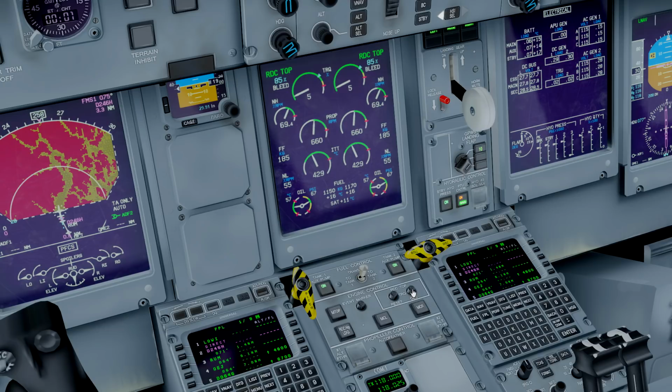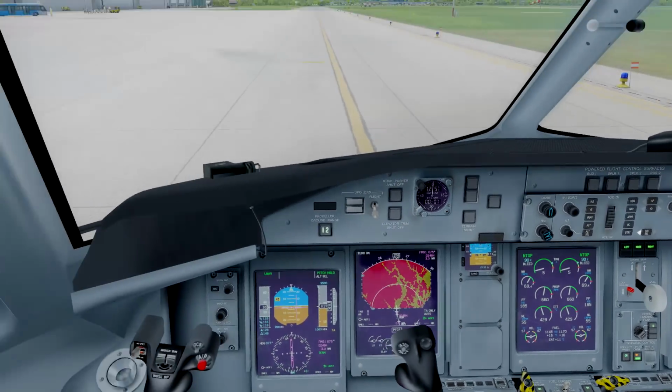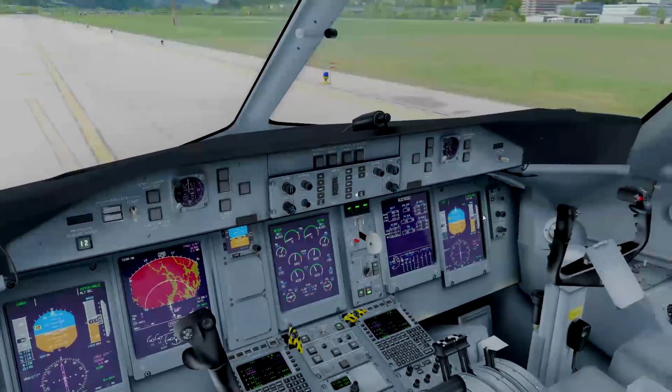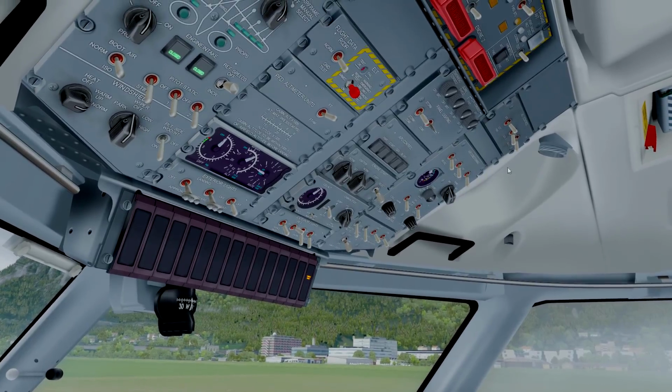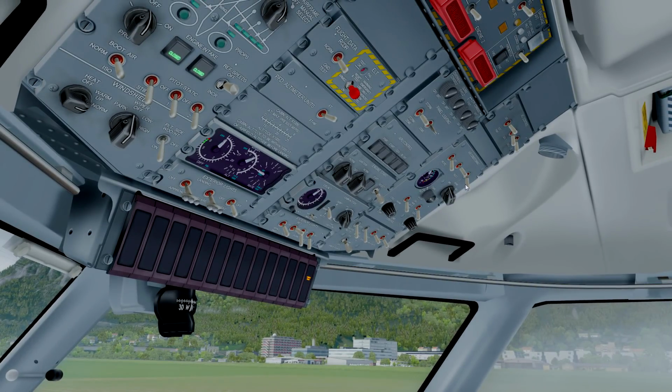And in that way, by clicking this switch, you can reduce the performance during takeoff. If you're doing a reduced takeoff and the runway is long enough, you can leave the bleeds on during the departure and use a reduced takeoff thrust setting. But if the runway is rather short, if the terrain is challenging, or if the runway is wet and you want all the performance available, you may want to consider leaving it at 90% and then turning off the bleed of the engines.